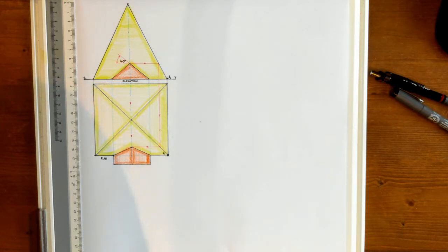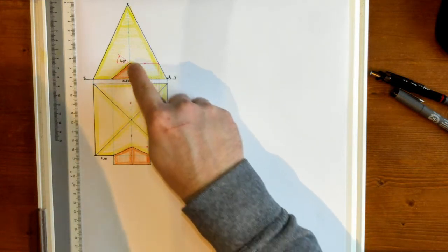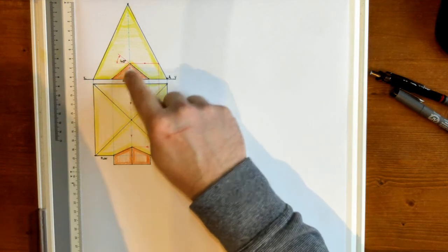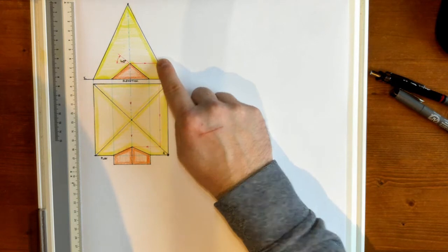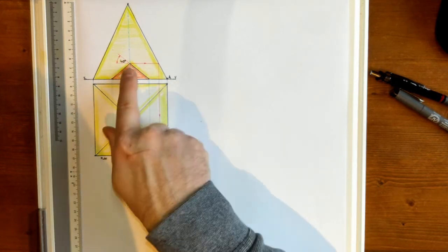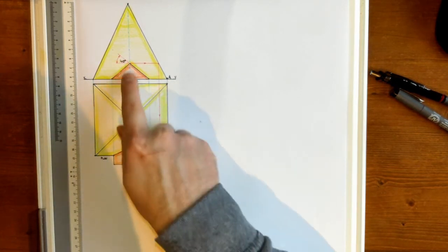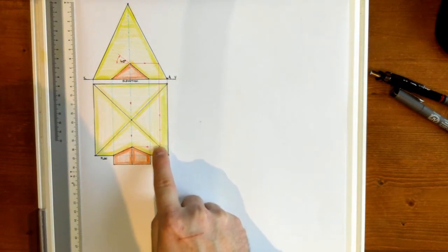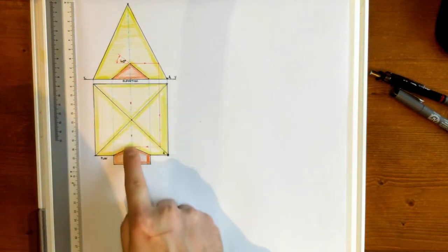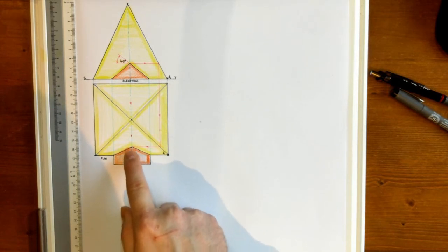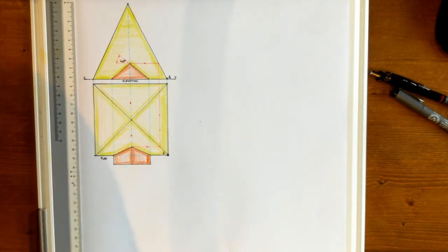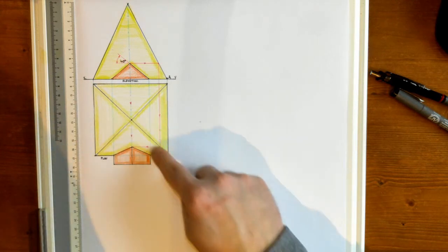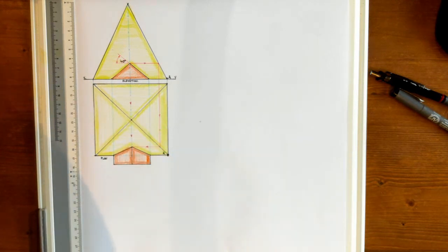Now, just to bear in mind, when you draw this front triangular piece, you're given the measurements for it, fine. But there is one point in the plan view that you must transfer in order to find it. Transfer it across to the edge, drop it down to hit the line here, and bring it across to meet the line coming straight down. That will locate that back point, the intersection between the front entrance to this pyramid structure and the actual surface of the pyramid itself. So very important to bear that in mind.